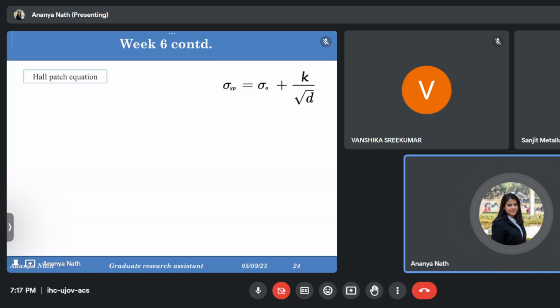In grain refinement, we are having some new grains out of the old grain. So if the old grain was of this much size, and the new grain is forming inside the old grain, obviously the new grain will have lesser size. So grain refinement has taken place. Refinement means giving rise to smaller grains.